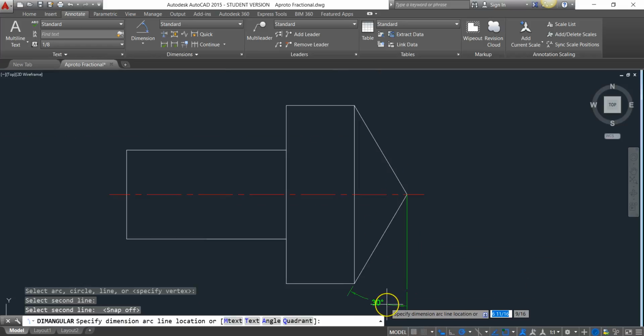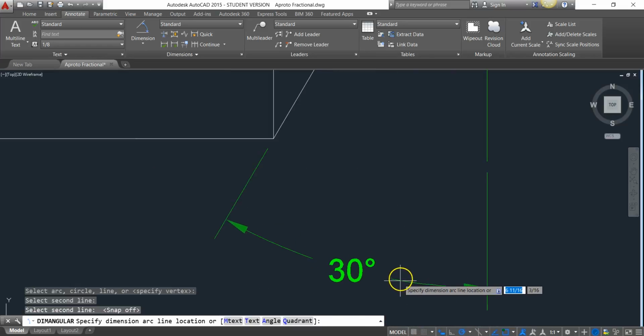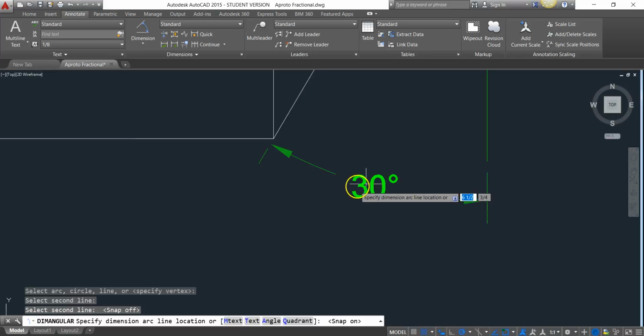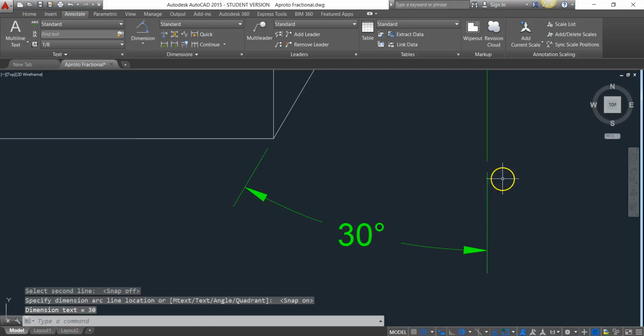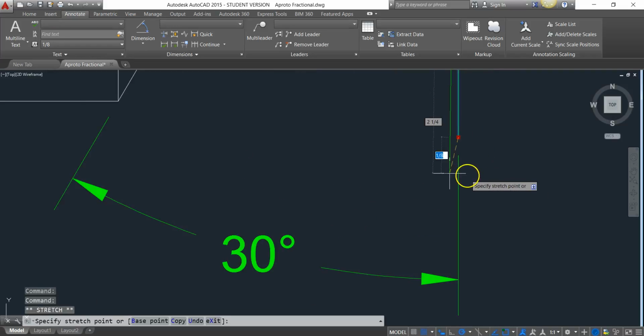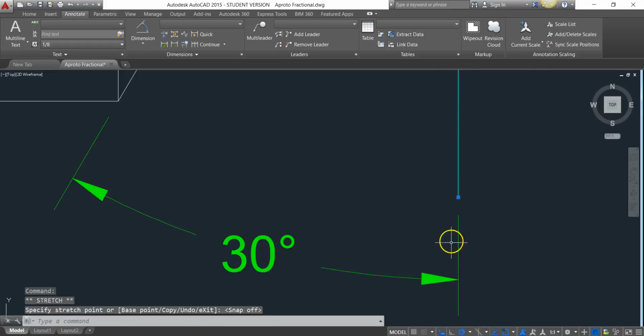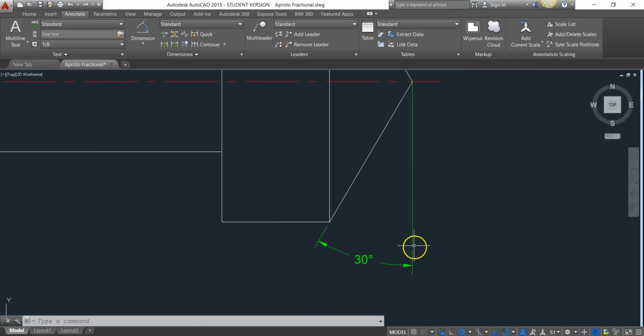Once you're ready to add this dimension and you want it to be able to snap, go ahead and make sure F9 is turned back on for a snap. Now I can go 1, 2, 3. And you can see that right now there is a gap between my dimension and really what we'll consider as the extension line. So if I pull this down, it's still going to have the same issue. So what we need to do is figure out a way to get my extension line right here up all the way to the top of this drawing.